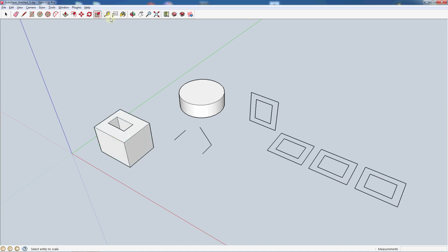All right, we have a few more tools that I will show you on the basic bar. The first one here, we have the measurement tool. This does two things. You can physically measure a length of something, so you can go point to point. Here it says 10 and 25/64ths, or kitty corner, we could say 14 and 27/64ths, things like that. So you can double check if you need something a specific size, you can double check that is what it is. The other thing it can do is create guidelines.